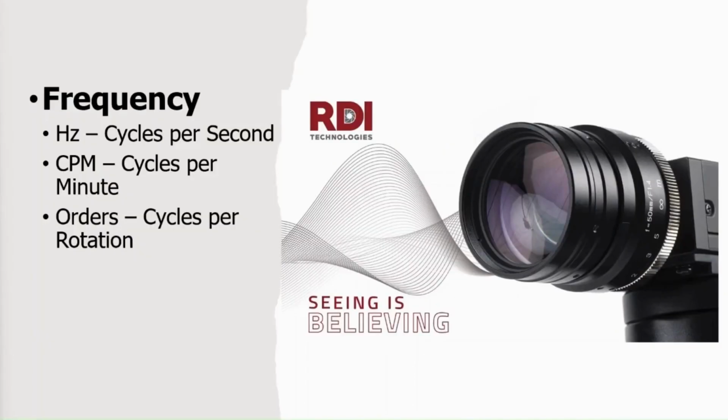And so there are three ways to express a vibration frequency. Hertz is cycles per second, CPM is cycles per minute, and in the case of rotating equipment where the rotational frequency or the RPM is known, we could express the frequency as orders, which is cycles per rotation.